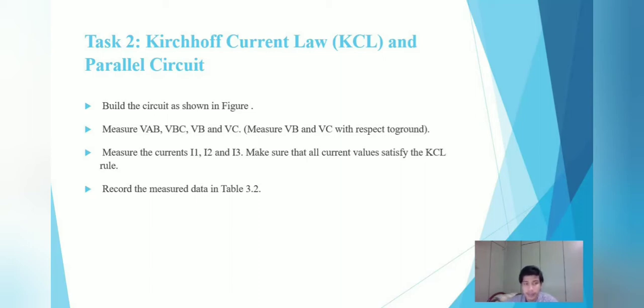Third, measure the currents 1, 2 and 3. Make sure that all current values satisfy the KCL rule. And last, record the measured data in Table 3.2. Thank you.